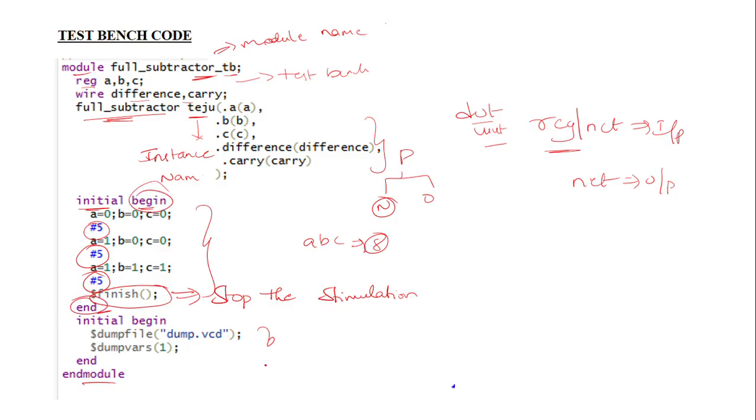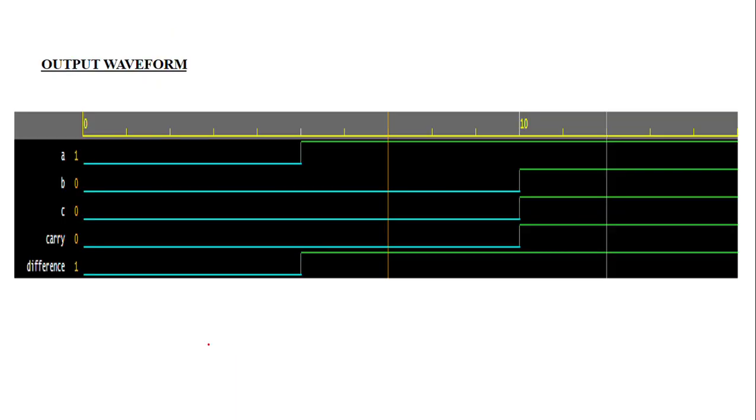For these 4 lines, as I say in every video, the code is executed in EDA Playground. In some compilers or RTL tools there is no need to mention these 4 lines, because they directly give the waveform, as it is built in. But when you want to generate a waveform in EDA Playground while running, you have to write these 4 lines and then end with endmodule.